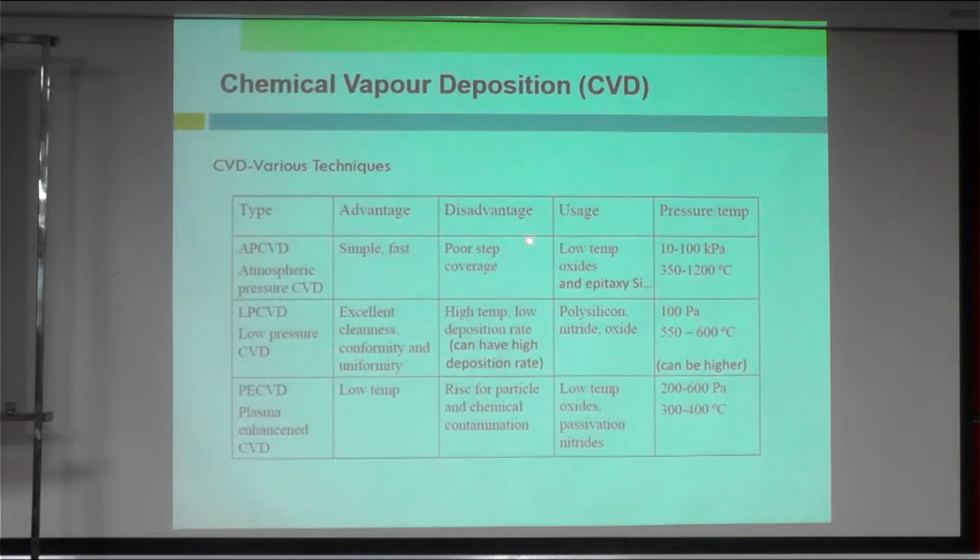As for disadvantages, step coverage is similar to an evaporator. For LPCVD, high temperature and low deposition rate, though it can have a high deposition rate as well. But there is a risk of particle and chemical contamination in PECVD.